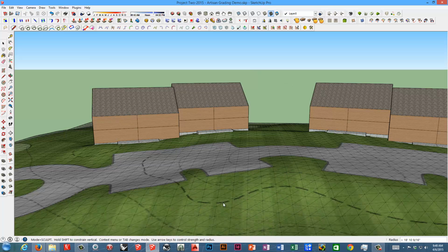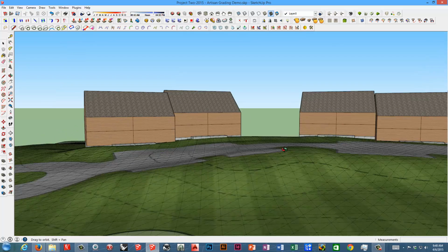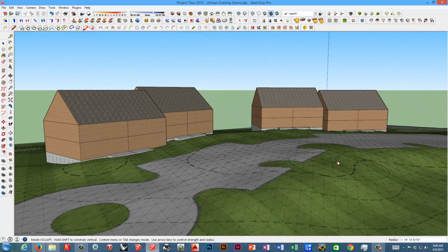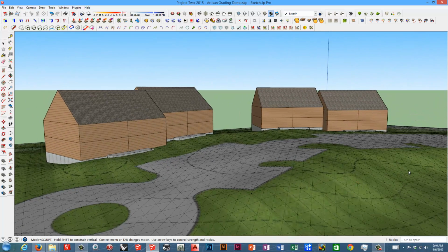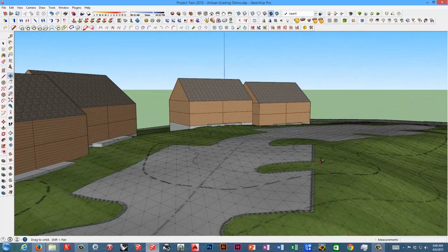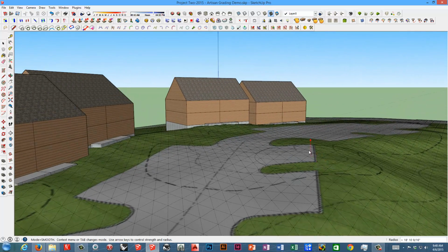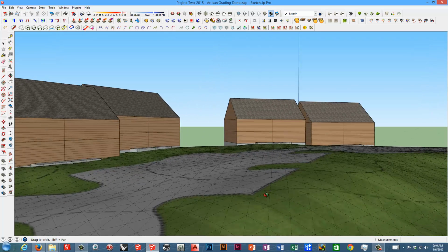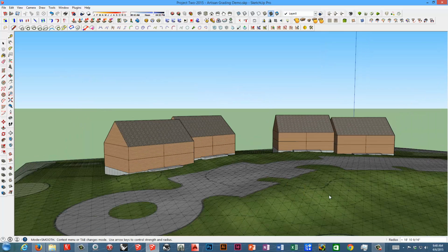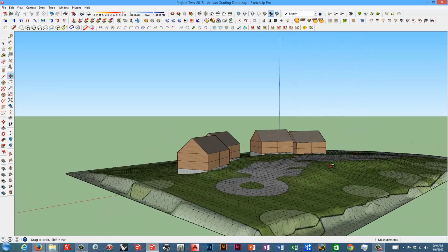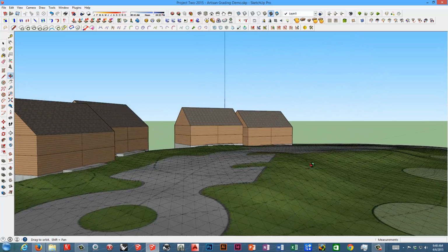Again, sometimes you have to work your way back out to move the adjacent areas up, otherwise you'll get that kind of fall off right at the edge there. Switch to smooth mode. I'll blend that back a little bit. And I'll come in with this on these embankments too, kind of smooth that off a little bit. And if you get a spot like that that just looks a little high, again, bring this down, switch to sculpt, just kind of refine that.